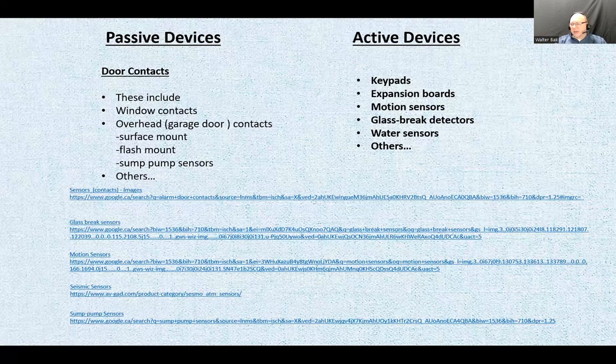There are three things that are going to happen. One is going to be the high pitch at the beginning of the glass breaking, that shudder, high pitch sound. It is also going to be associated with the low frequency rumble of the whole membrane, the glass, moving. You might not hear it, but it's there. But that microphone is going to hear it. And also, it's going to be associated with a sudden pressure change in the room. If those three things are present, the glass break detector is going to trigger. For the most part, there could be some cheap ones, not all of them, because there could be hundreds of different manufacturers that maybe skip one or two of those. If those three are not present and the thing still happens, then you could have a false alarm.